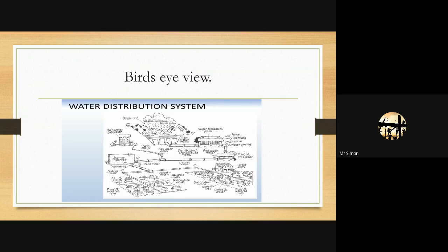We've got water tanks in some areas that hold water up high that can be gravity fed, but then it's piped out. Oh, zone meter. Look at that. Looks like they have little meters all throughout the system, so they can tell how much water is passed through. This is where they collect a lot of information, where they can determine the efficiency of their system. So water is piped out to all the homes. District meter, like your neighborhood would have one, and then it goes to each home, and in each and every home, there is another meter saying how much each of these different homes has used. Metered area, district metered area. Look at this. This is a great little system here.